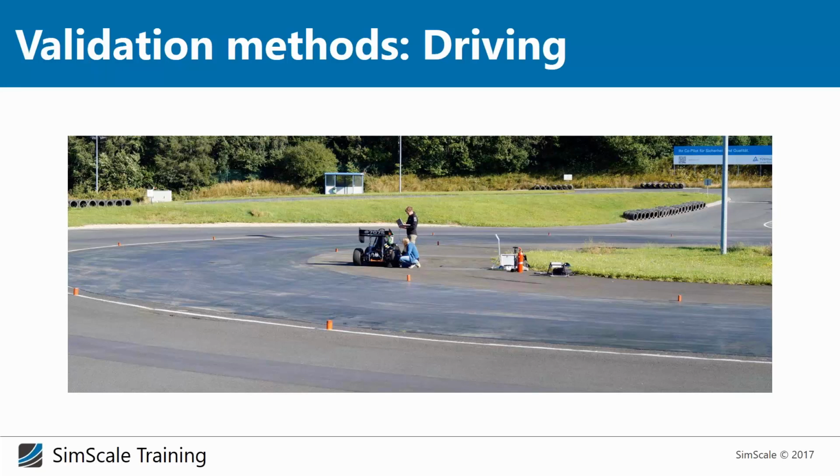And if your aerodynamic devices really are doing what they should do, then I think the lap times with aero should be faster than those without aero. All those are not the perfect validation method, but if you do some of them, you can move in the right direction. So those are pretty simple validation methods without having to spend time in the wind tunnel.